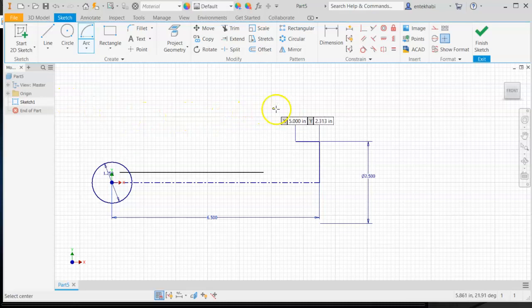Pick a free point for this arc, any place that is not projected from any point, not locked in any specific location. Then snap to the end of the horizontal line. Our last point, we are not sure where it's going to be until we add other information.